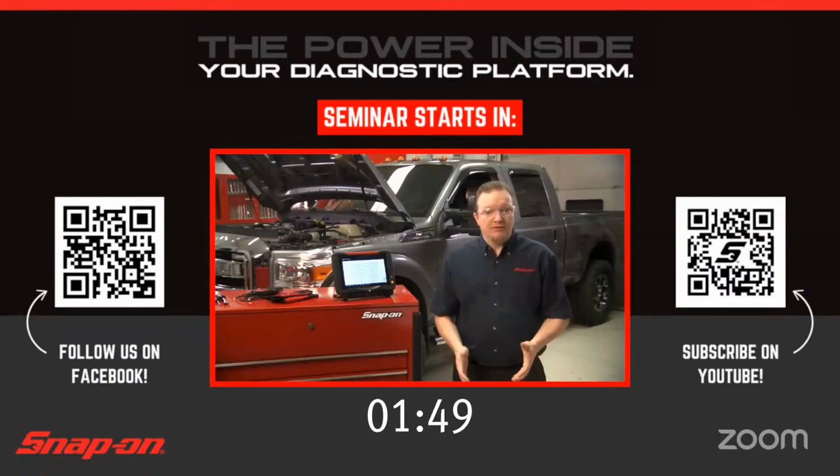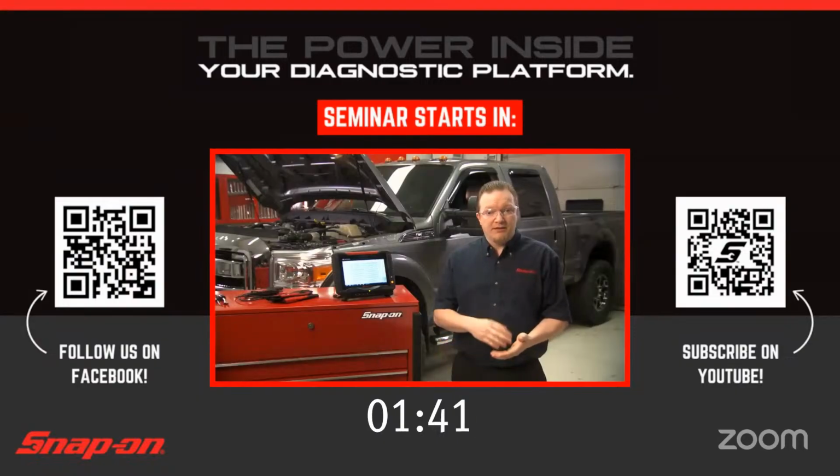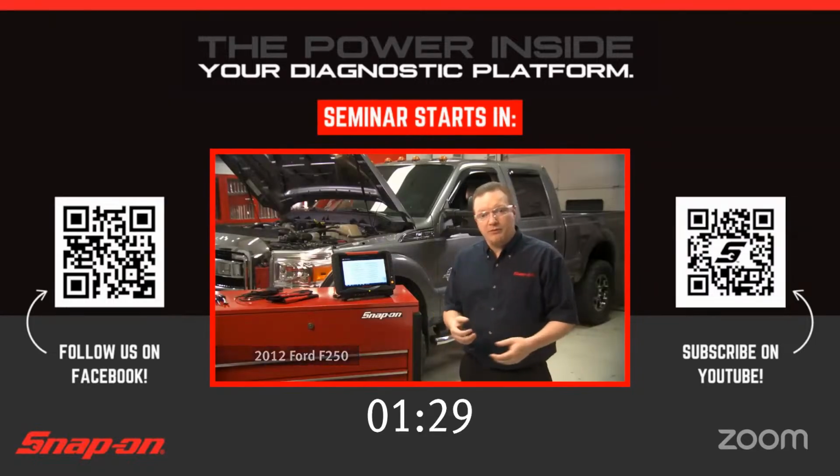On a lot of vehicles, especially diesel trucks, when you replace a fuel injector, you often have to code that injector into the vehicle's computer. What that coding does is tell the computer how much fuel that injector is going to flow, because every fuel injector flows a different amount of fuel. On this Ford truck, it's a pretty easy procedure, so let's walk through it.